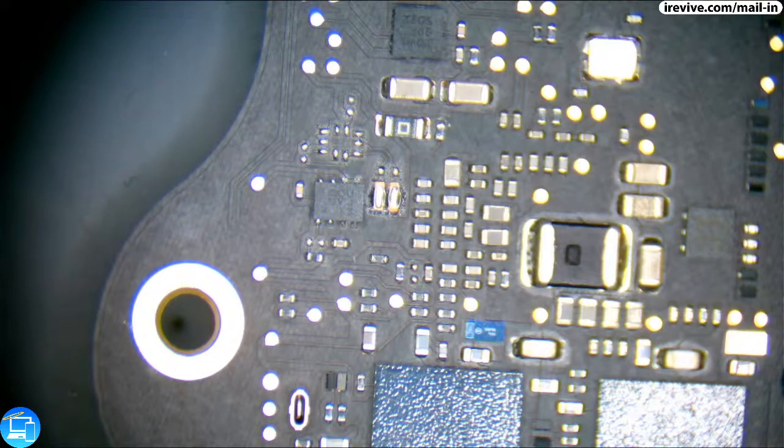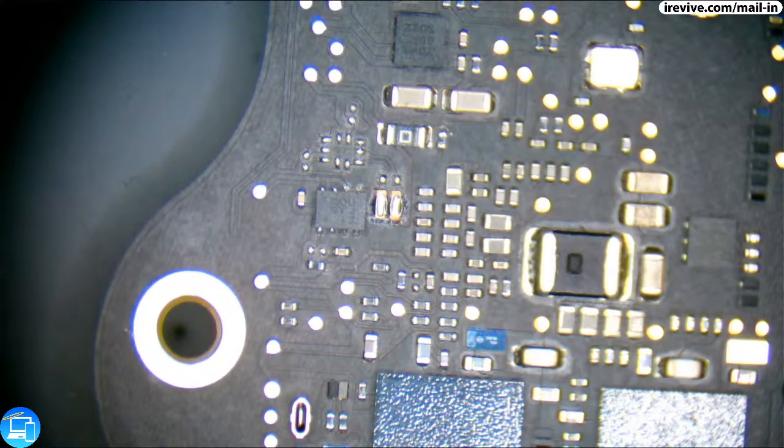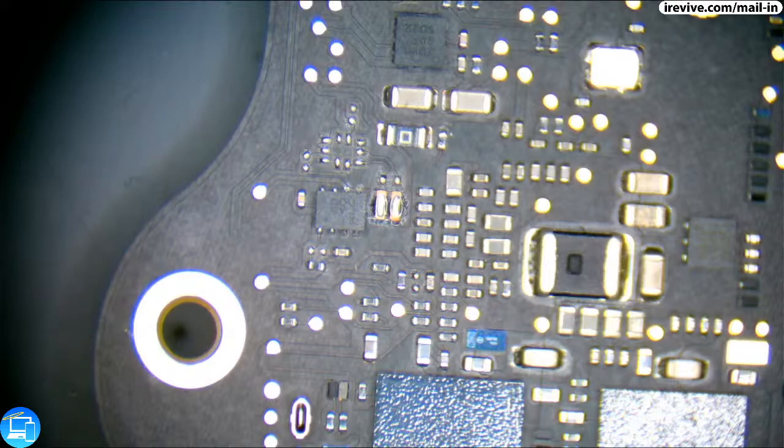Now the voltage in between, which is PP3V3 TBT T CMP, will change if this turns into ground. Now this is not ground, but I think the CD3217, when it turns on, is actually supposed to ground this out, which drops the voltage on our CMP. So that's probably normal, what we have going on here.